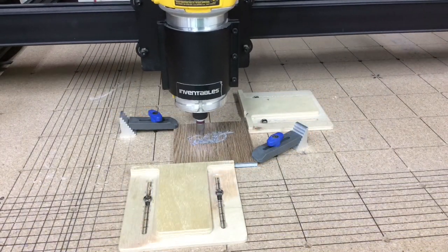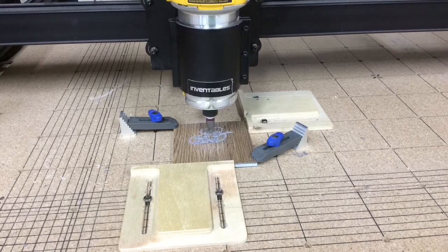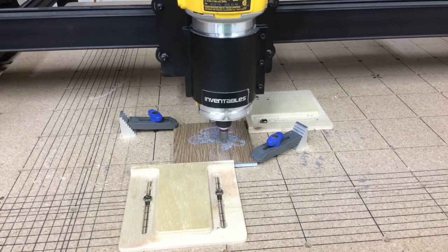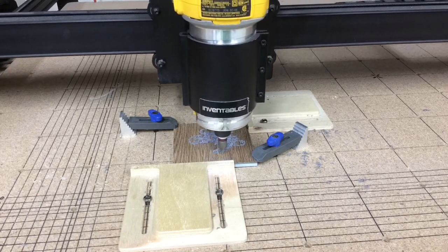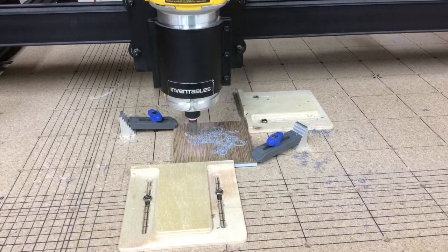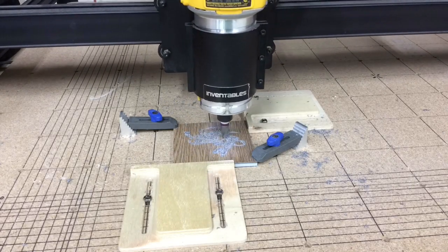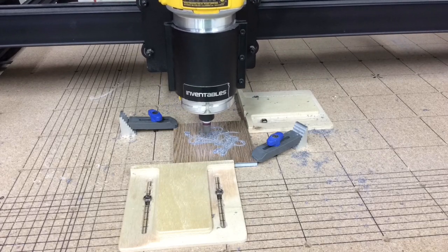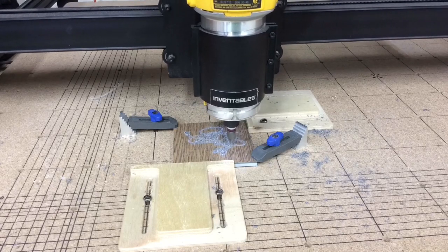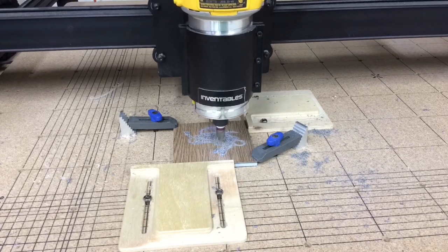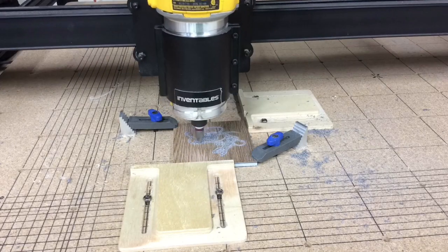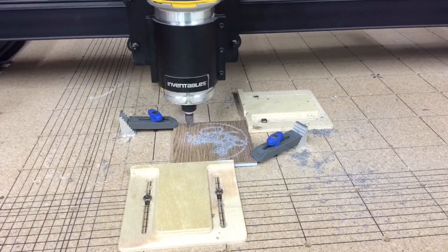I've carved a lot of the different vinyl floor samples, and one of the things that I have noticed is the hardness of the material does vary. This particular one is actually quite soft. So what I did is actually change the settings from what I said earlier in the video. So for this one I started with a depth of 0.03, and I did the cut. And then I came back and added another 100th of a point. So it was 0.04 to be able to cut as a finishing pass. And that gave the best results for this particular floor sample.